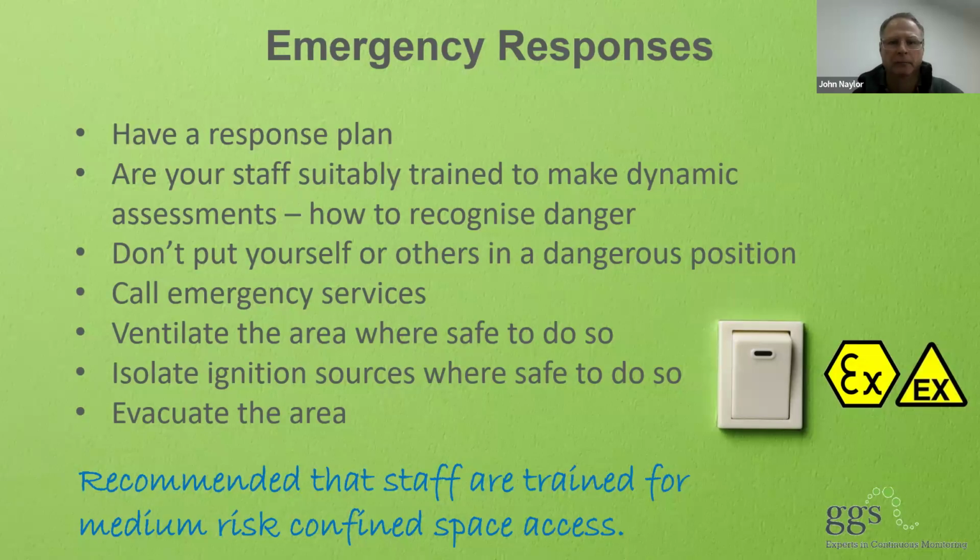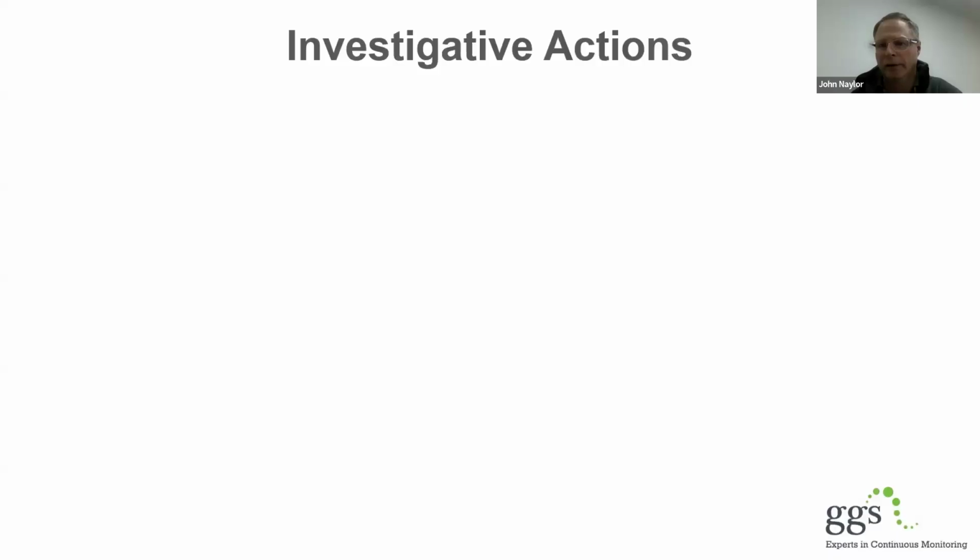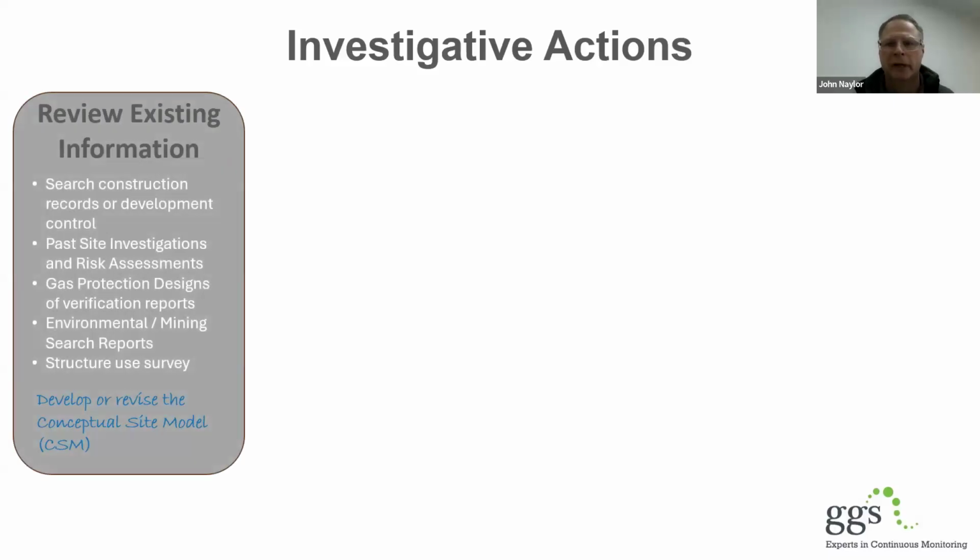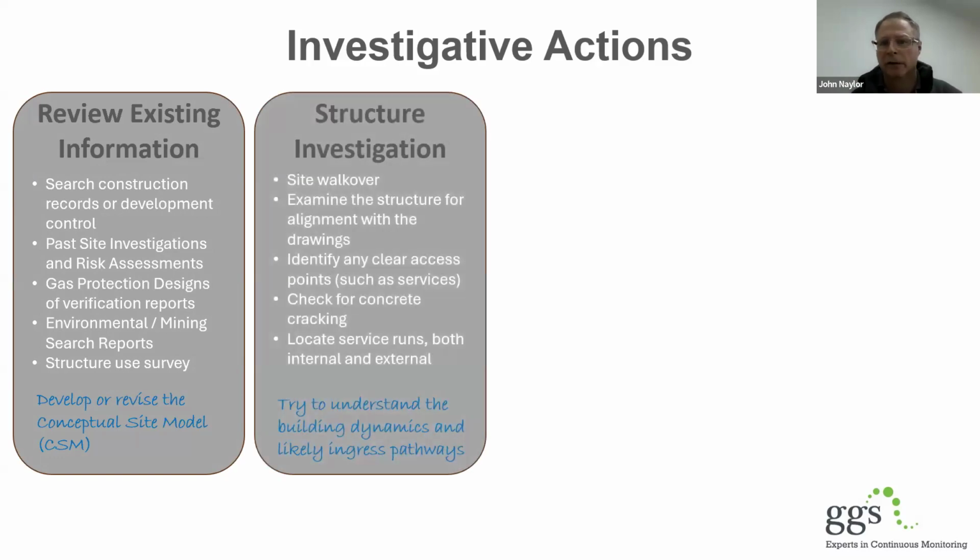Okay, so investigative actions. So what are those? Well, the thing that most consultants will be familiar with is, let's go and have a look at the data that's already there. Desk studies, historical maps, environmental searches. There might even be borehole logs from the BGS or even past site investigation and risk assessment data you can go and look at. Then from that, develop your conceptual model or modify an existing conceptual model. There's another few things there we need to look at.